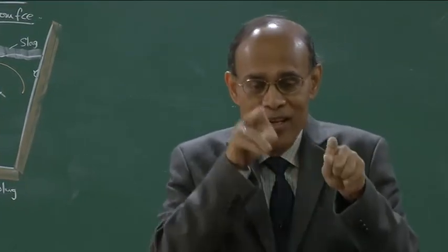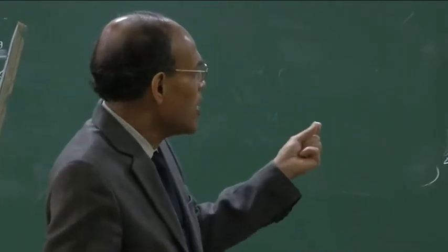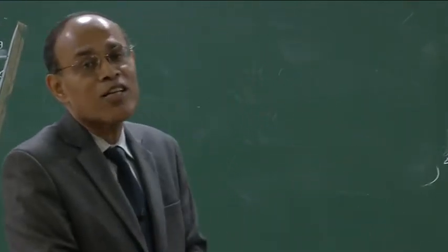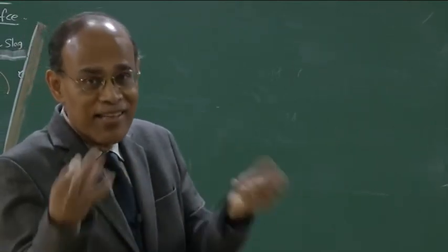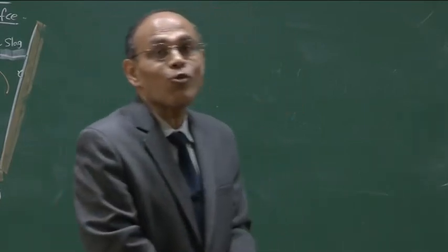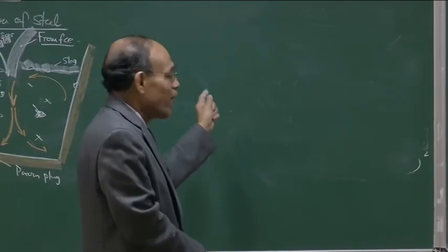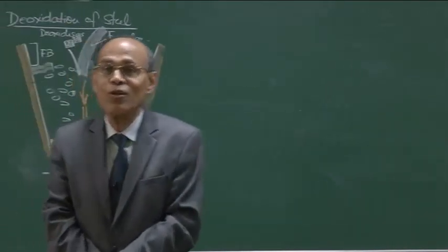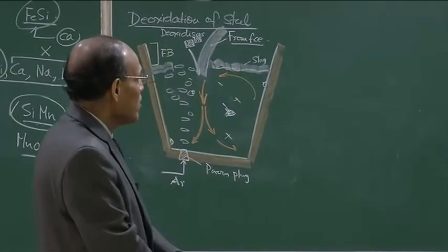But as far as deoxidation product and melt equilibrium is concerned, there is sufficient indication from the occurrence of the deoxidation process, given the rates of chemical reaction, given the rate of heat and mass transfer, that there is no nucleation barrier, and that the assumption of equilibrium is not too bad. It will work, and it will give you reasonable values of deoxidizers that you will calculate offline and apply in your plant practice.